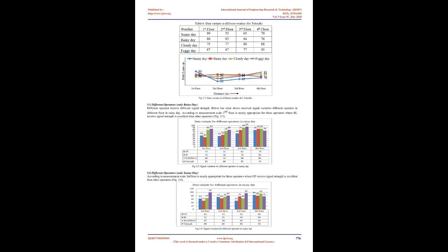See the signal strength measurement scale. Values closer to 0 are stronger signals. Signal strength can run from -51 dBm to -113 dBm. Values closer to -51 dBm are stronger. A signal beyond -98 dBm is not considered strong enough to work properly.